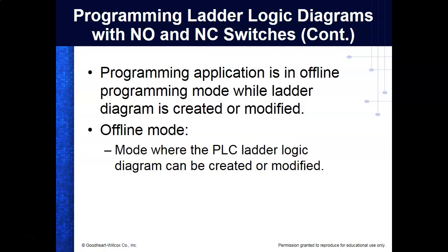Most of your new PLCs have what we call a remote mode, and that's what mine is in. In the remote mode, you can switch it between the run mode and the program mode with your computer. It does it automatically. You saw it where it says it's in the run mode, do you want to switch it? And I said yes. And then it says, okay, do you want to switch it back to the run mode? And I said yes. And then it says, okay, do you want to go online so you can see what the program's doing? And I said yes. So normally in this class, we will put it in the run mode.